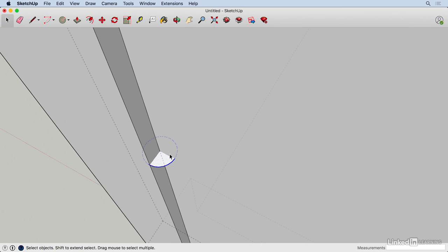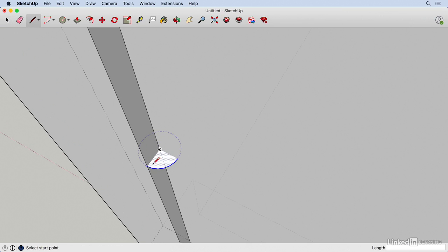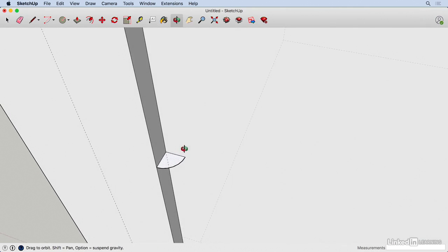So if that bothers you, if you don't want the circle on the inside, we can go ahead and separate that out using the line tool and go from endpoint to endpoint here so that this piece of pie is separated from the rest. And now with our back edges turned on, and again, that was the letter K to toggle that on and off, I can select these edges here and it stops because I've separated that out. I can hit the delete key and now I'm left with this profile.